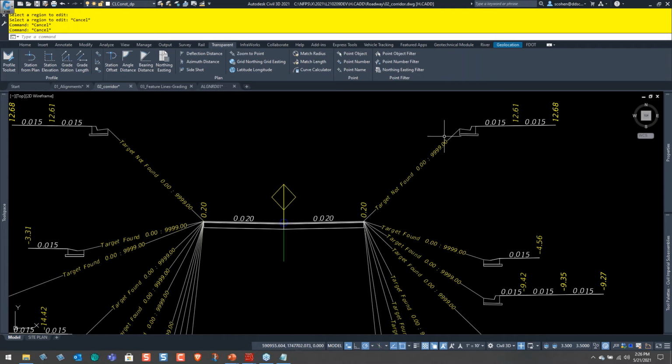Now, what you'll see here is I have a type F curb, okay? I then have a utility panel. I think that's what this is here. And then, actually, no, this is sidewalk. That's right, this is sidewalk. And then I have a simple one here that is my building target, because the biggest thing I need to figure out is the elevation pads. The way I do that is I simply trace in 2D where the buildings are supposed to be as a feature line. And then I set elevations based upon what the corridor model is doing,